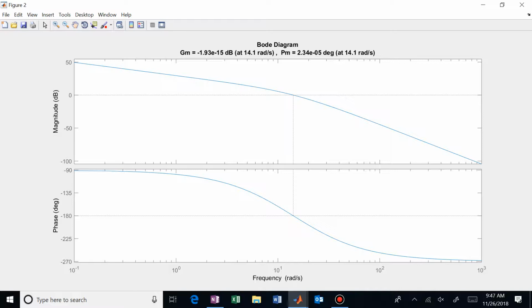What's the phase margin that we want? 30, but we need to introduce a safety margin, right? So let's say we introduce a 10-degree safety margin. So now we're looking to achieve a phase margin of 40 degrees. What's that mean? Well, now we look and see if we can find minus 140 on our phase curve, and where does that happen in frequency?